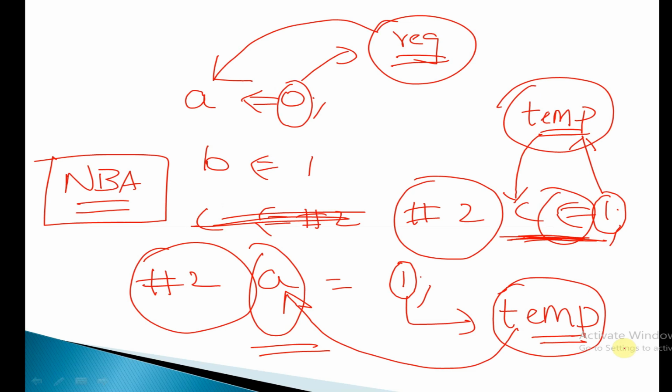If you have A non-blocking of 1, then what happens? 1 will be stored inside a temporary register, and after that it will be stored into this particular A. Since there is no time delay specified here, at 0 time unit only everything is happening. If you have a time period specified, then according to the completion of that time period, your right hand side value which has been stored inside the temporary register will be updated towards the left hand side. So this is how a non-blocking operator works.